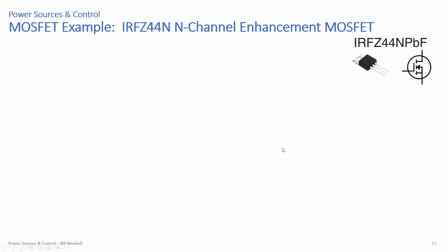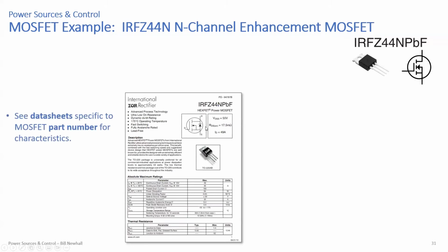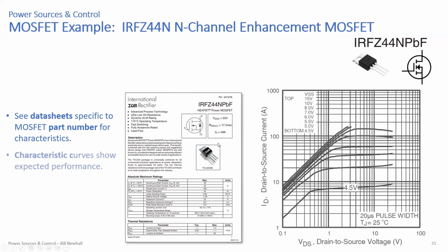Let's look at some real curves. So let's look at the curves and data sheet for the MOSFET you're using in lab, this IRFZ44N. It's an N-channel enhancement MOSFET. We'll talk about that. So this is the part right here. What you really have to do is look at the data sheet for a particular MOSFET, specific to its part number, to look at the characteristics. Then you can dig into those data sheets and find the characteristic curves. These characteristic curves will show you the expected performance.